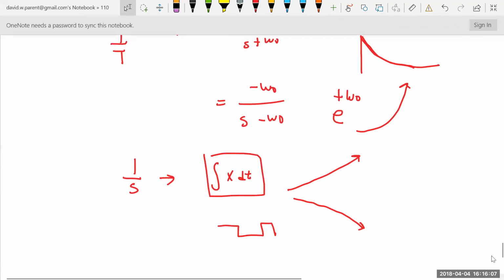This is the system. So anything where the real part is greater than or equal to 0, you're going to get exponential increase, or it'll turn into an integrator, right? And yeah, if you have 1 over s squared, it's a double integrator, right? You will get a system out of control, which really is going to be next time.